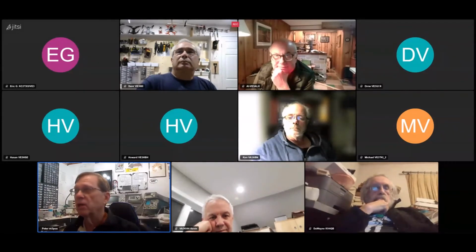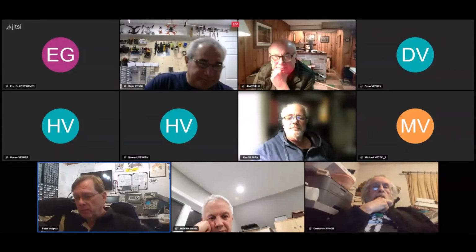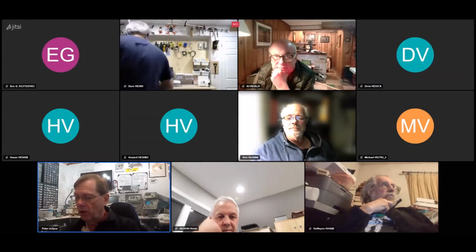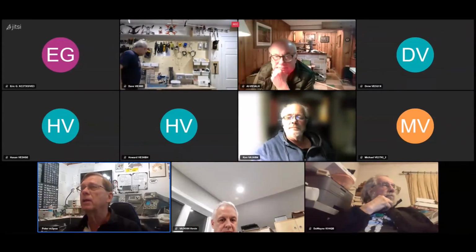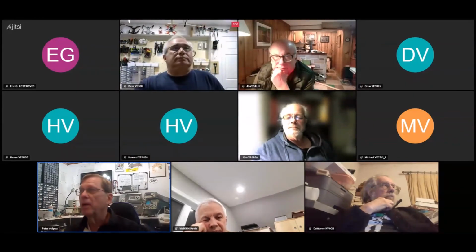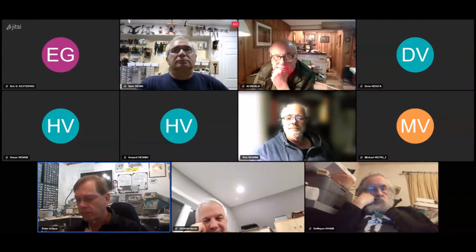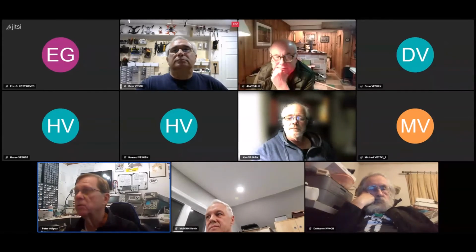Well, it turns out a few things can go wrong, and one of them I blame on Dave, but we'll get to that in a minute. There were a couple of lessons I had to relearn on this project. Many years ago, I learned the hard way that tantalum caps have the positive end marked with a black band and not the negative. But apparently I had to relearn that lesson last week as well, because I soldered it in backwards and let the smoke out of that cap. And then when I took that cap off, I lifted a trace. So then I had to patch up the trace.